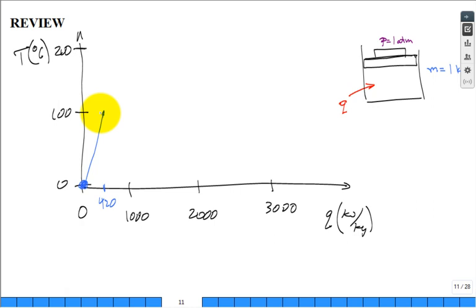As I'm starting to add Q, the temperature goes up, up, up, up. Then it hits 100. Does it continue to go up? Does it go flat? Does it go down? What's happening? Flat. It goes flat. And it's got to march out from this point out to the next point, 2,257. So it's going to go all the way out to 420 plus 2,257, so it goes all the way out to this value of 2677. Try to draw it to scale, staying at 100.